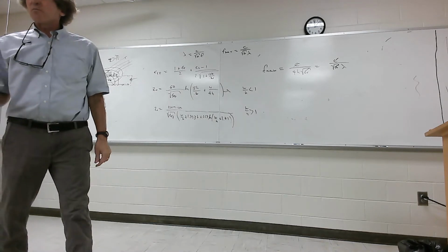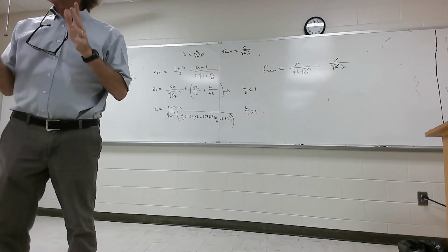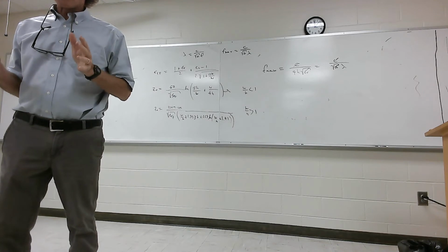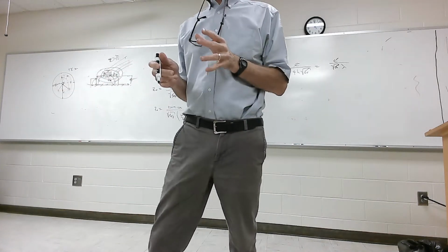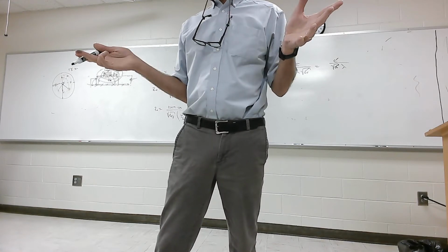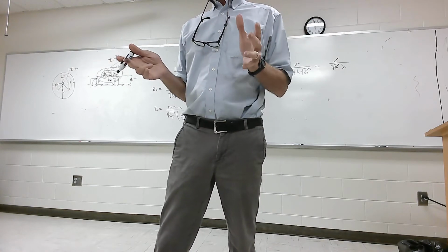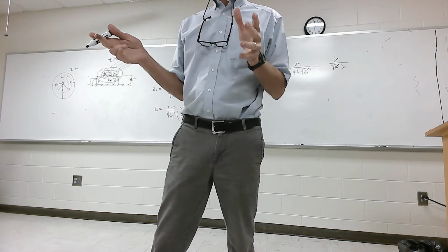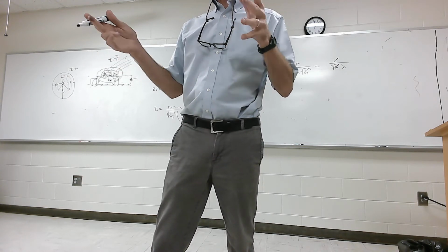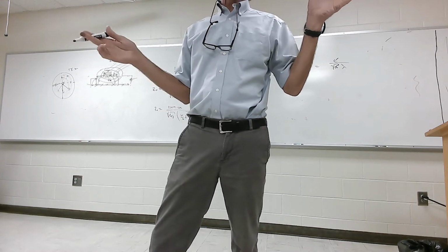Think about it, all right? C over F. If it's 300 megahertz, it's 1 meter, right? If it's 3 gigahertz, it's what? 10 centimeters, right? 30 gigahertz, 1 centimeter. You're basically up there at optical kind of frequencies, actually just a little lower than optical.